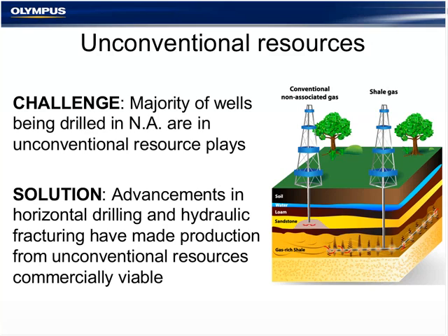Part of a mudlogger's profession and science is capturing samples of these cuttings at very regular, close-spaced intervals. It's typically over the shaker screen that samples of well cuttings are collected. Using time-based calculations, the precise depth of the formation that the cuttings came from can be calculated.